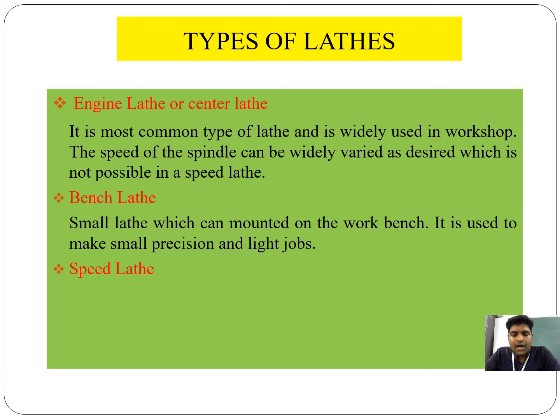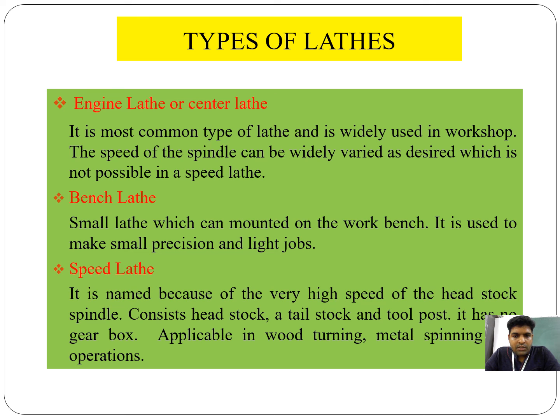Next one is the speed lathe. It is a high speed lathe due to the maximum speed of the headstock. It consists of headstock, tailstock and tool post. There is no gearbox in this lathe machine. This is basically used for wood turning, metal spinning and similar operations.